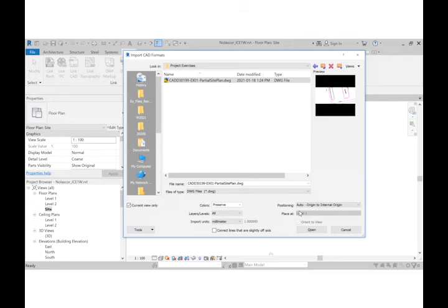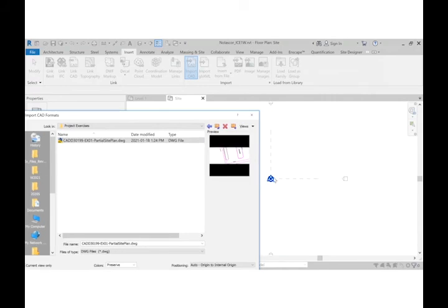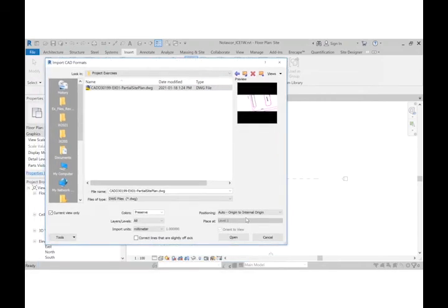So if I am correct, my CAD file will go to this origin. The origin from my CAD file will link to the origin of the Revit file. That is origin to internal origin. And you want to use that technique if you are coordinating with somebody using AutoCAD to import files, even if they're linked files, using the same origin. Okay, so they match up.